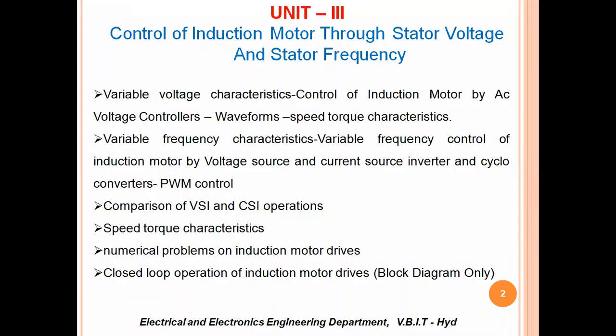We know what is AC voltage controller. An AC voltage controller converts input AC voltage to output AC with variable voltage. So we can regulate the voltage magnitude using the AC voltage controllers. In the variable voltage characteristics, we need to control the stator voltage. Remember this word, because unit 3 deals with the stator.